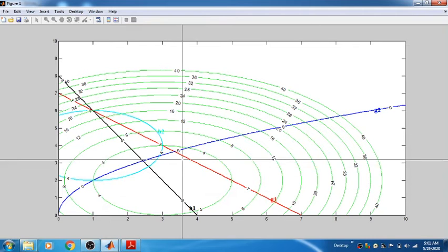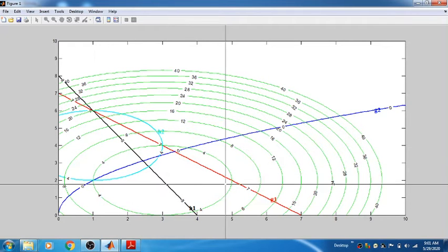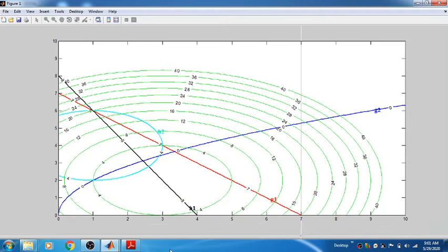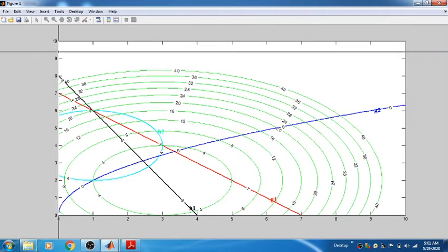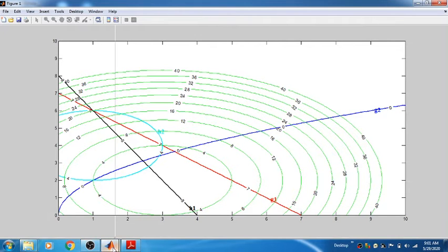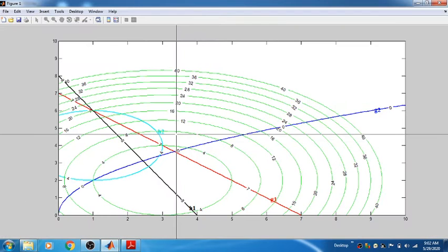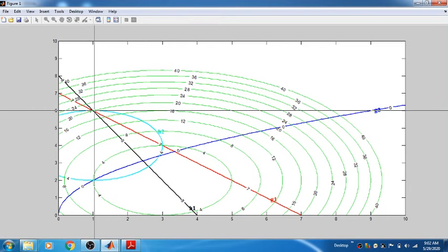It is showing elliptical, but actually it is circular. Why is it showing elliptical? Due to this aspect ratio. This x1 is this much, and x2 will be this much. The aspect ratio is not the same. You have to keep the aspect ratio the same there. By this way, x is equal. Once the program runs, it will show you the circular contour.